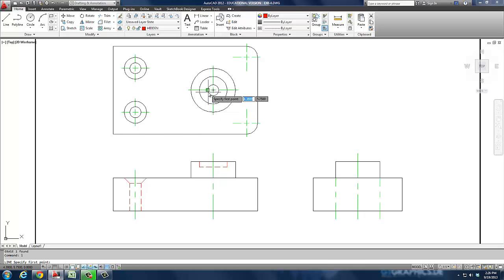So I can do that same thing, use that same principle to come off the quadrant right here and line it straight up right there, and then go all the way through the hole. Same thing happens on this side. From the quadrant to perp, all the way through to perp again, and then these lines just get erased, and there's my hole. So that's a counterbore. Literally what happens is it's flat on the top, steps down to a cylinder area, and then steps down to a hole that goes all the way through.